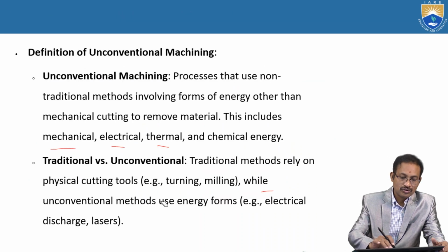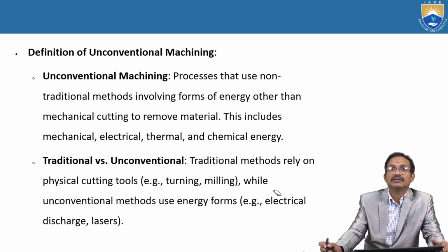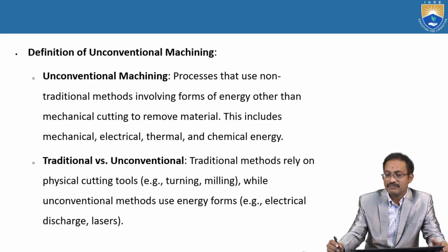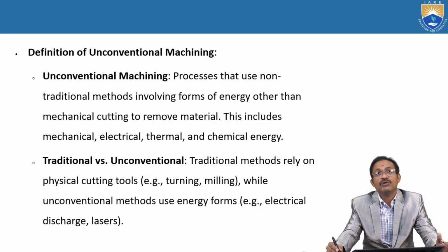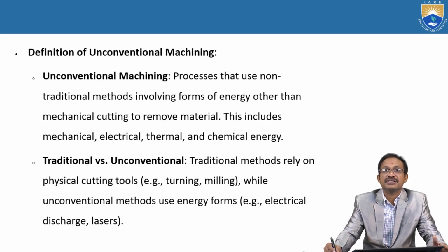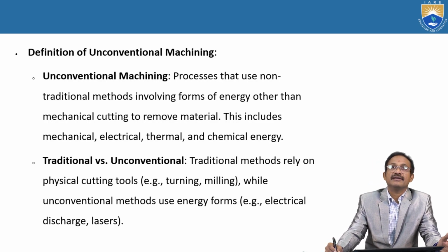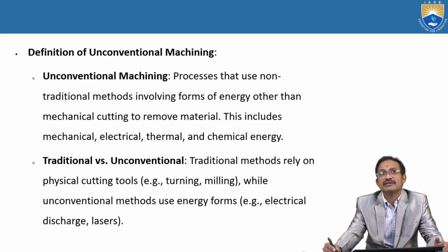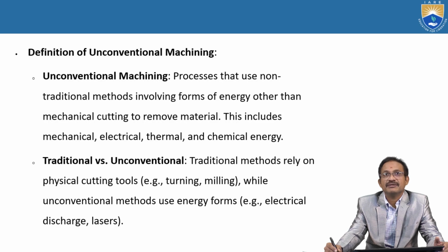Students will have to understand where to use the unconventional machining processes and where to use the conventional machining processes. Obviously, the unconventional machining processes are very expensive, and at the same time the material removal rate is somewhat less when compared to conventional machining.